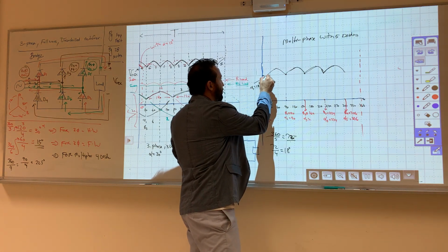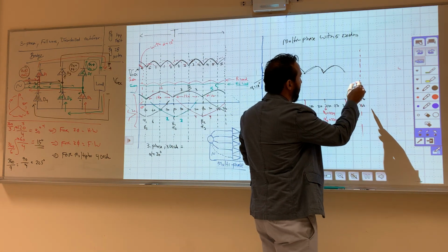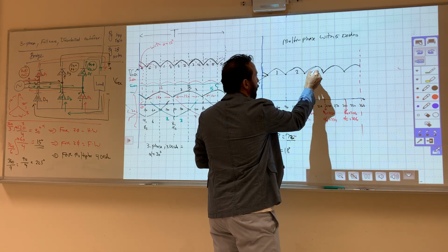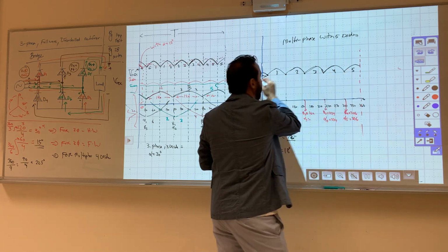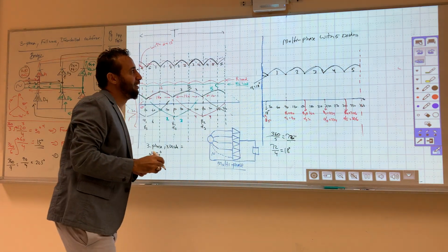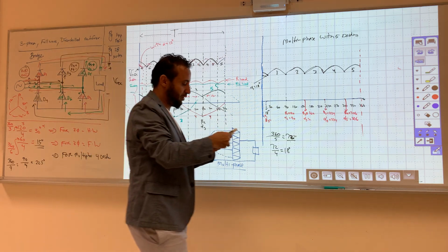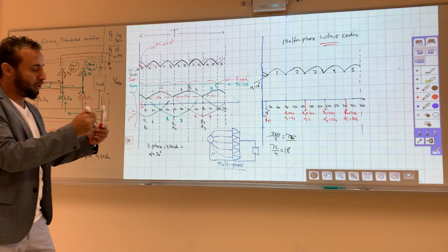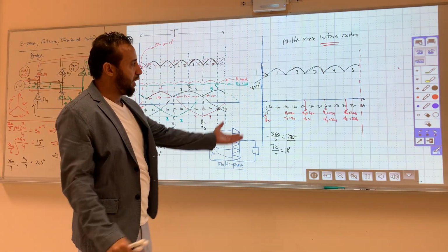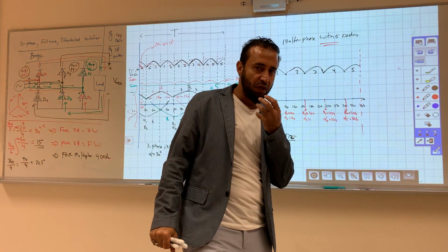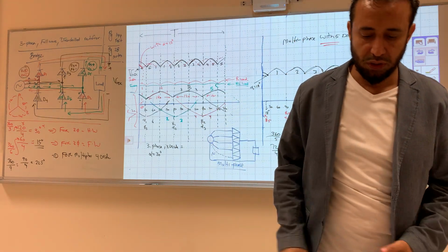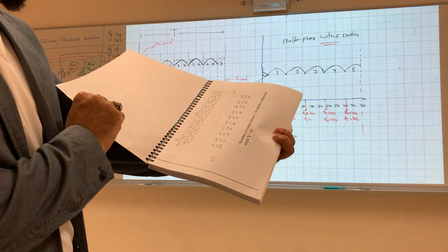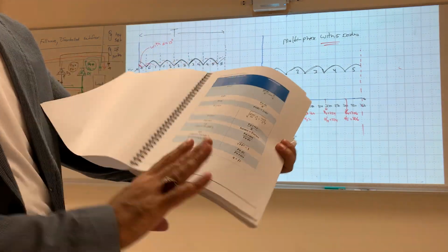See here, guys. That's what you will have. So I have 1, 2, 3, 4, 5. That's my output, guys, for multiphase with 5 diodes. Okay? And those are the alphas. Make sure you know how to calculate this. So if I give you 7 diodes, 4 diodes, 10 diodes, make sure you know how to, you can follow this in page 25 and in page 26. And those are the equations.